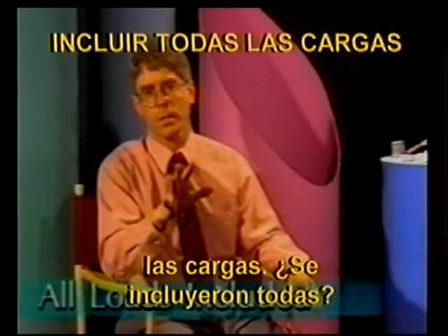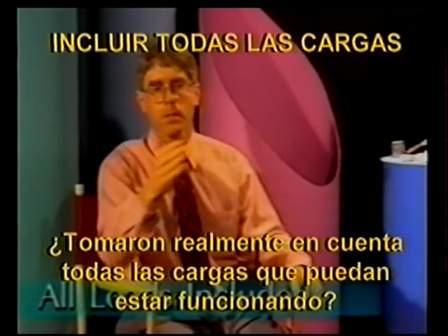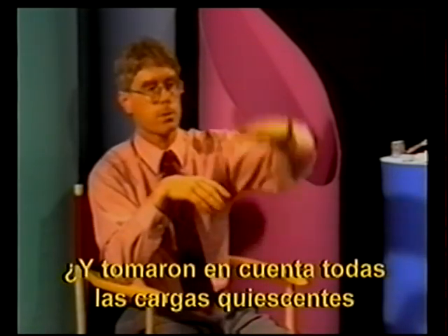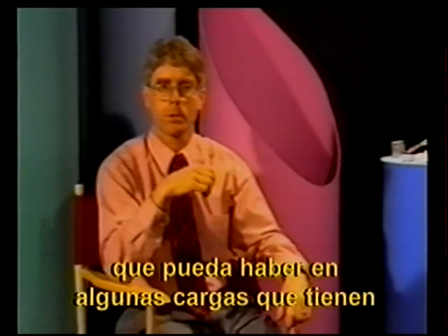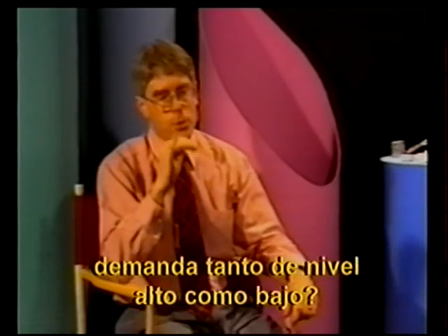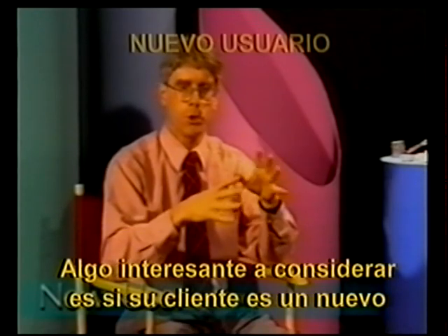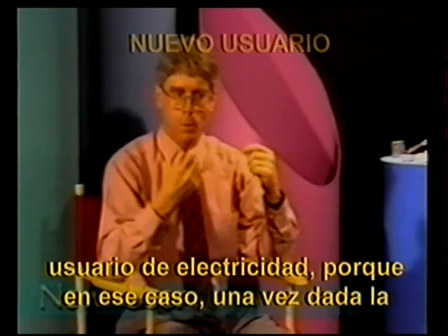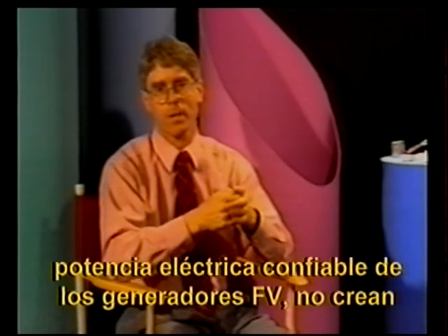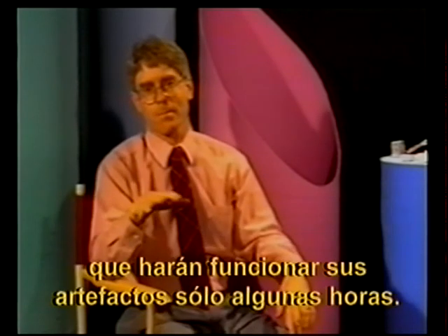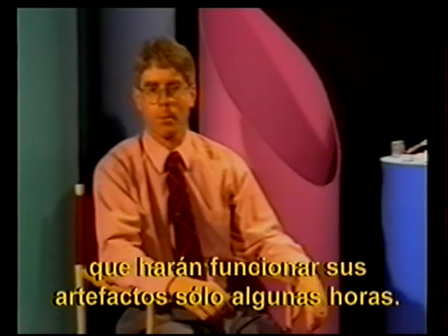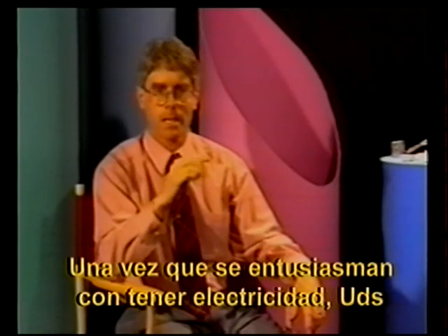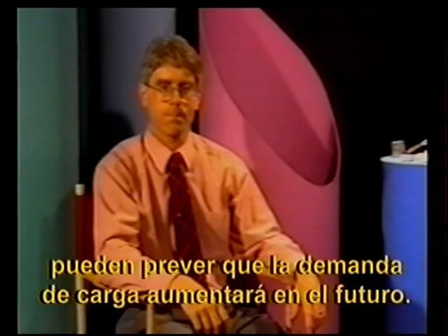Have all the loads been included? Have you really taken into account all of the loads that might be operating? And have you taken into account the quiescent loads that might be in some loads that have both a high level and a low level of load demand? An interesting thing to consider is, is your client a new user of electricity? Because in that case, once given reliable electric power from your photovoltaic generators, don't believe that they're only going to operate their lights or their appliances for a few hours. Once they get excited about having electricity, you can anticipate that there'll be future load demand growth.